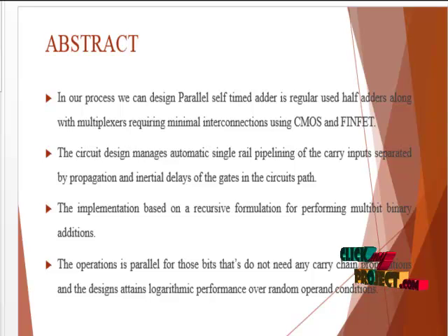These dual rail signals can be represented in more than two logic values, and therefore they can be used to generate the bit level acknowledgements when a bit operation is completed. Finally, completion is sensed when all bit acknowledgement signals receive the high values. This carry completion sensing is used in our example pipeline adder, which uses the full adder functional blocks adapted for the dual rail carries.